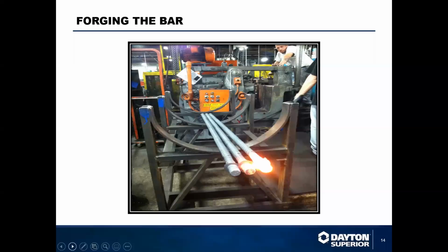Now, the Dalbar system is basically taking a piece of rebar, putting it into an induction heater and heating it up to about 2,400 degrees. At that point, we run it through a series of presses. This shop here is in Tremont, Pennsylvania. Typically, it is a 4-step press that comes down through and takes the rebar.